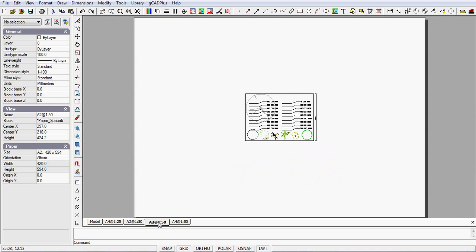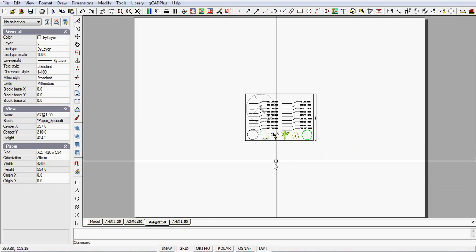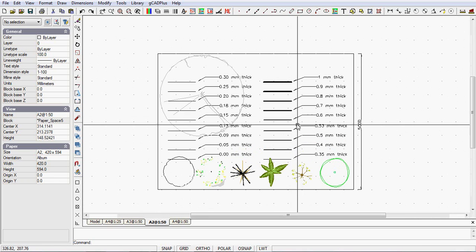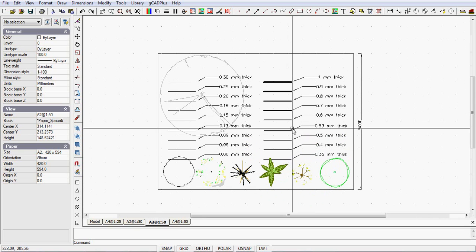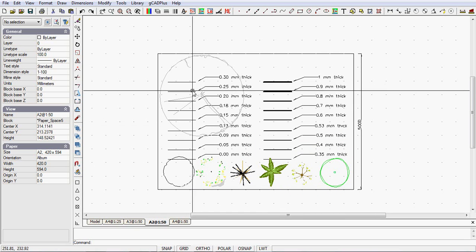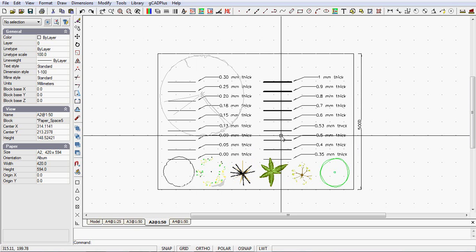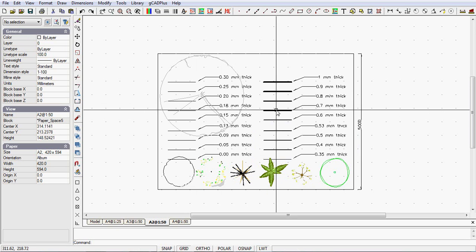And if we go to an A2 sheet here, you can see that the design would be just sitting down in the corner of the sheet, but once we roll in on it, can you see that you can still work with this series of line types in that 0.4, 0.5 and so on. So the take-home lesson is, at smaller sheet sizes and relatively small plot scales, you're going to be working maybe in the 0.25 up to 0.5, but as you go up in paper size and up in scale size, you might have to bring some of these others in line. So that all seems fine.